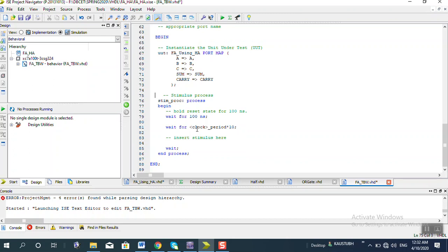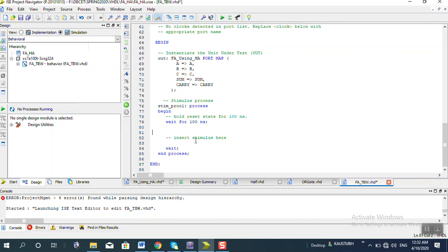Okay, so as we did in the previous lecture, here also we'll do the program for the test bench waveform. So stim process 1, let it be wait for 100 nanoseconds since there is no clock. Delete this. Then say A is assigned with not A.